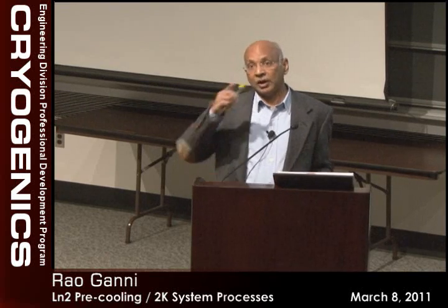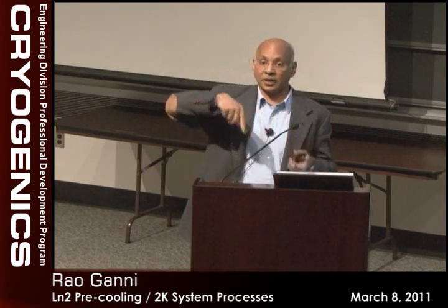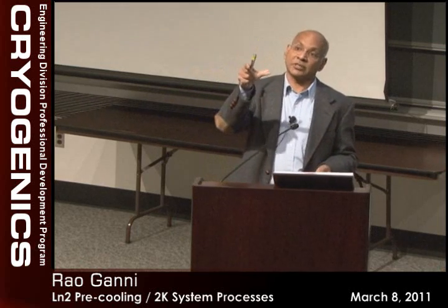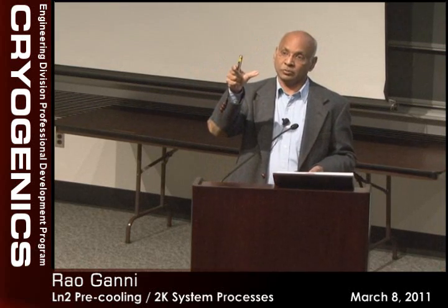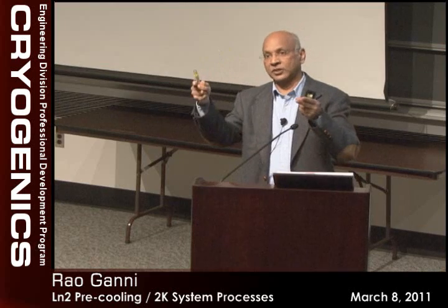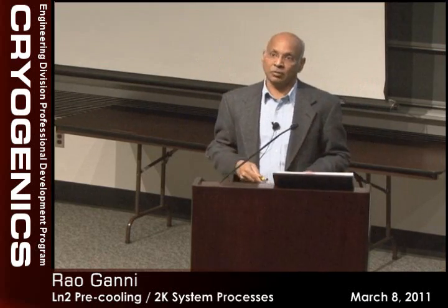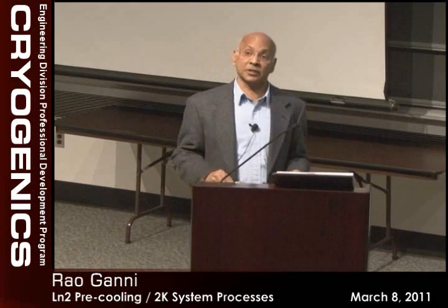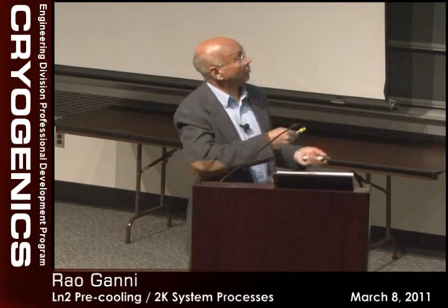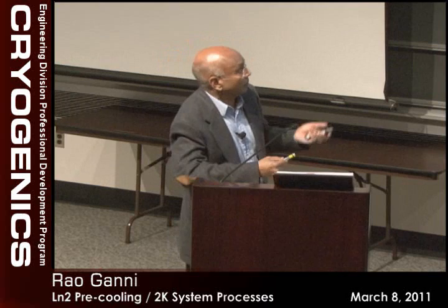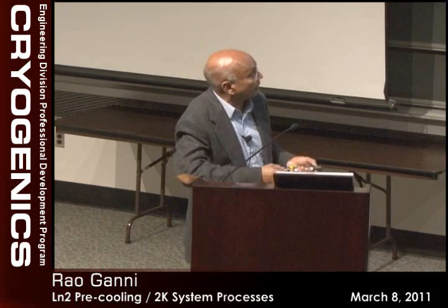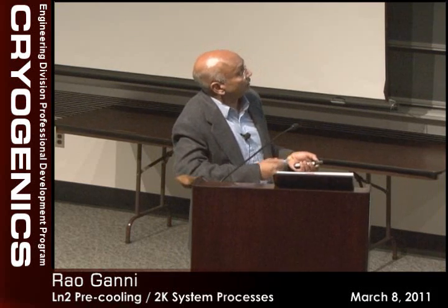So to do that, you have to make sure the valve has a thermal loop, so that the valve itself is not allowed to see one side 80K and one side 300K, by allowing it to stabilize. And so that's why we specify all these into the specifications. That's how we were building. From the 80s, I'm involved in it. All these purifiers I was involved in.